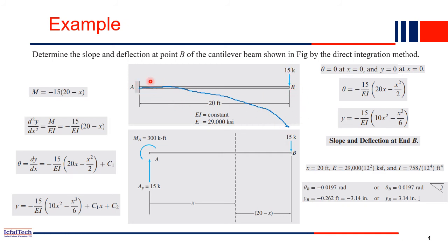Now if you see, this is a fixed end support, right? Fixed end support means that the slope or the deflection does not start from the support itself, unlike the other two. Let me draw it for the hinge support also. For the hinge support, if you recall, we drew it in the last slide also. You have a hinge and a roller, and if some load is acting on it, then the deflection always starts from the support itself.